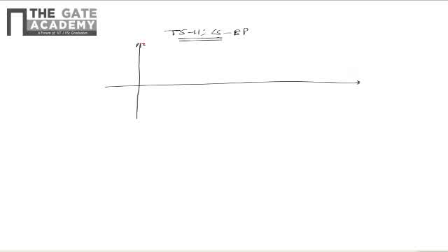is as shown in the figure. The Bode magnitude plot has an initial slope of minus 20 dB per decade and it has a magnitude of 24.1 at 2 radians per second. From 2 radians per second on, it decays at minus 40 dB per decade and it has a magnitude of minus 12.05 at the point marked.